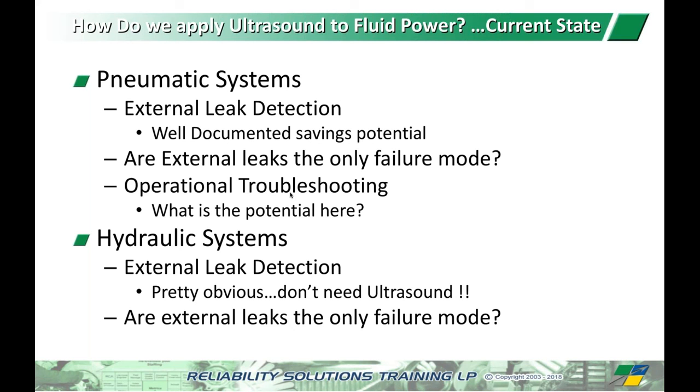that we're not using. We've done a fair bit of work on this over the years in using this technique to really troubleshoot operational type issues on fluid power systems, both pneumatic and hydraulic. And most of that involves using the contact probe and probing around various critical parts of the system, like directional valves and relief valves and isolation valves in some cases, filters and that type of stuff, to try to determine if you've got any internal leakage.